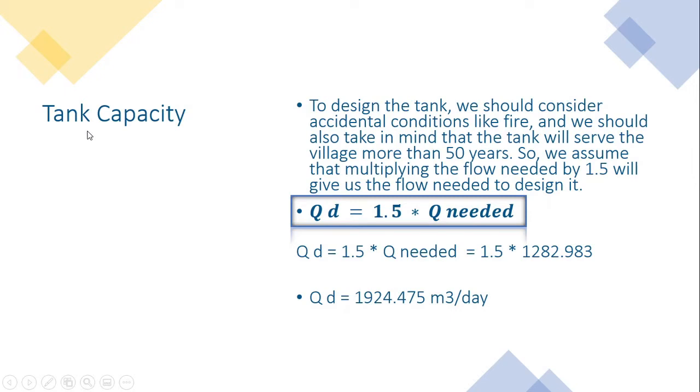And also the flow for designing the tank for storage. We should consider accidental conditions like fire, and we should also keep in mind that the tank will serve the village more than 50 years. So the flow for designing the tank will be the needed flow times 1.5.